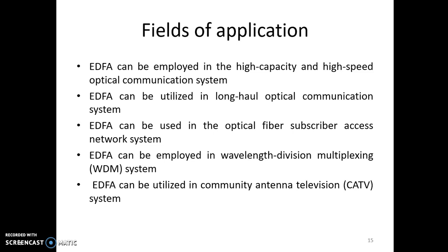EDFA can also be employed in wavelength division multiplexing systems, especially dense wavelength division multiplexing systems. Utilization of EDFA in WDM systems is able to solve the problems of insertion loss and reduce the influences of chromatic dispersion.